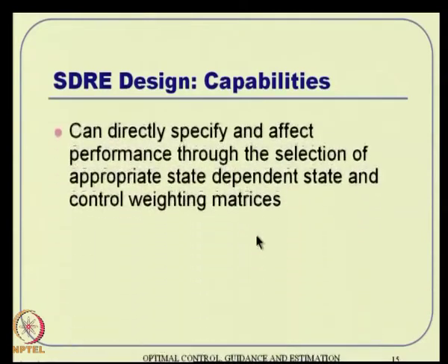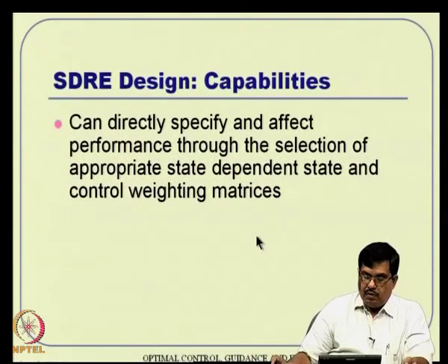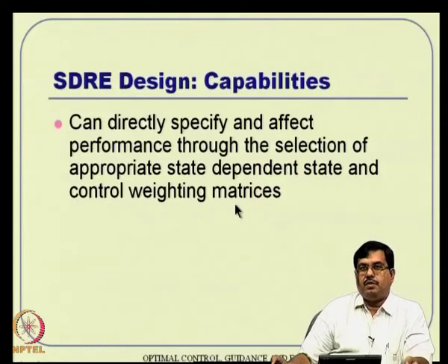Alright, now coming to a different thing, what are the capabilities of SDRE? This can be summarized something like this. You can directly specify and affect performance through the selection of appropriate state dependent state and control weighting matrices, that is Q of x and R of x matrices.